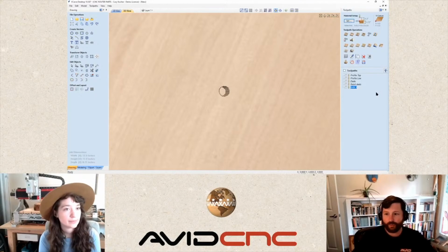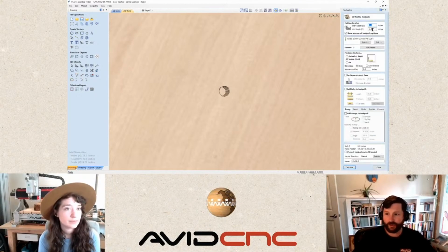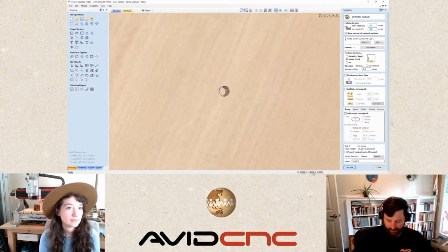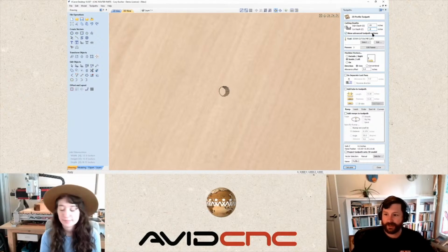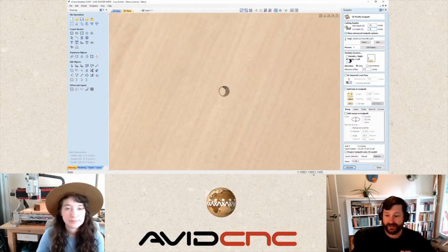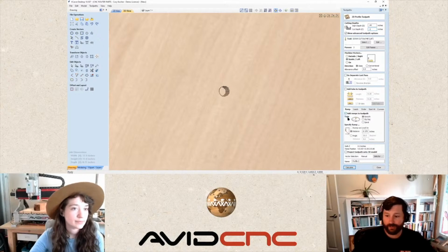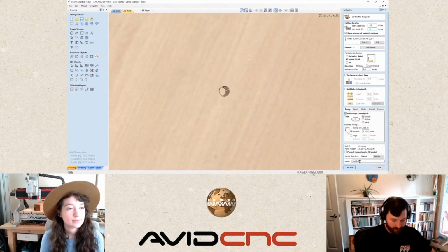And so let's just go ahead and do the final drill here, or to full depth. We're going to start it at 0.44 because that's where we left off. And then we're going to go to full depth, which would be 0.3. 0.3 would get us down to full depth. And all of the other parameters can stay the same. We want to make sure we check ramp, 0.375, drill 2.